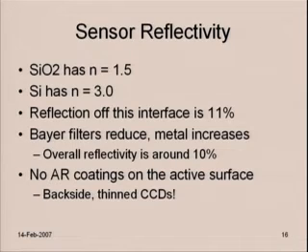The stuff that scales down less well is the wires that are taking the information out of the pixel and getting it to the periphery of the chip where you can process it. And so what tends to happen is that your fill factor, the percentage of the front of the chip that actually manages to absorb light, is going down as you make your sensors smaller. And this is only making the problem of having fewer electrons worse. So this is one of the reasons why when you look at a cell phone picture or something like that, you see really astonishing amounts of noise. It's because those sensors essentially count individual photons coming into the lens. They do. Even in reasonable amounts of light, they do.